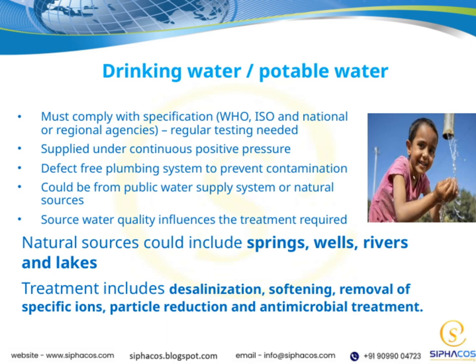These sources can provide us with raw water, but it's important to remember that this water often needs treatment before it's safe to drink. Treatment processes include desalinization, which removes salt from seawater, softening to reduce hardness, and the removal of specific ions that might be harmful or cause taste issues. We also focus on particle reduction to clear out sediments and microbes, along with antimicrobial treatments to eliminate bacteria and